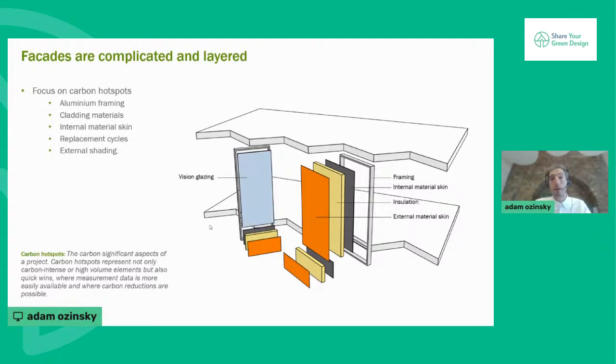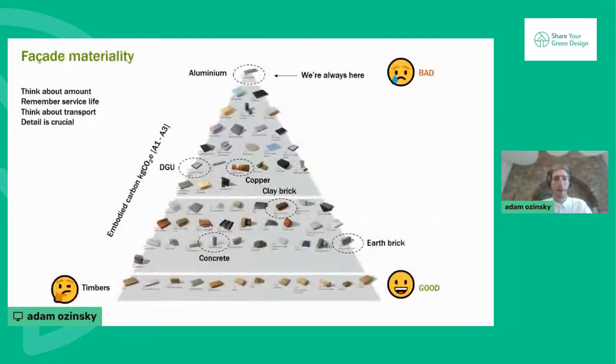Well, not something we'd considered a lot previously, and suddenly we're seeing, well, there's so much of it, and it's often an aluminium sheet, that it's costing a huge amount of embodied carbon. Similarly, external shading. Oftentimes it's aluminium, needs strengthening, and that's costing embodied carbon. Whereas you could achieve the same sort of performance by just reducing the glazing ratio, for example. So facades are complicated.